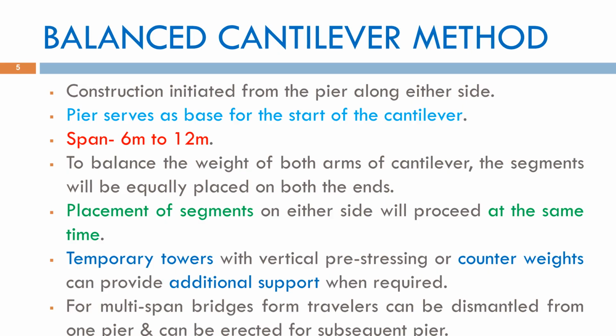This method is generally suitable for spans between 6 and 12 meters, especially where ground-based supports are difficult to install because of rivers, valleys, or busy roads. However, constructing the pier table requires careful planning and considerable time.